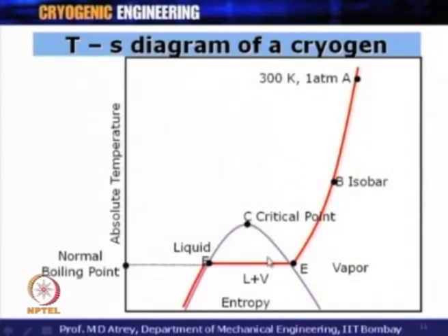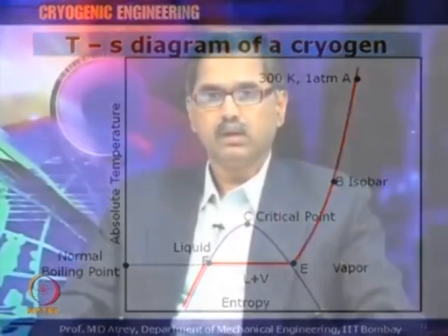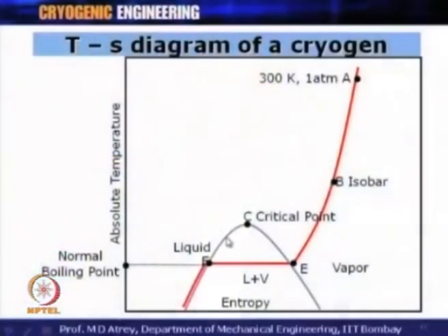Therefore, if I tell you any state of a gas in terms of temperature and pressure, you can immediately know the corresponding critical pressure and temperature of this gas, and therefore you will know whether it is in the gaseous state or whether it can be in the two phase region also. So, if I want to liquefy the gas, the pressure I should have is going to be less than the critical pressure, so that I can be in this dome.